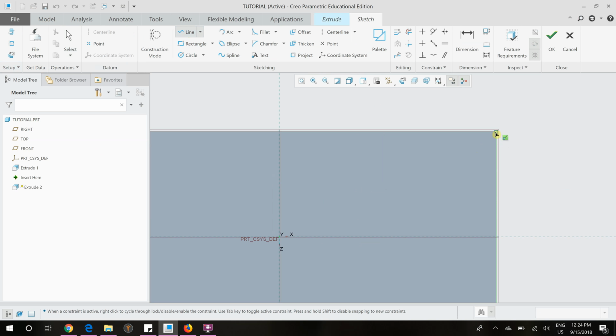So say we want it to be centered, let's say an inch from each edge. So we're going to measure down to the center of the hole. And now we can draw our circle. Let's say we want our screw holes to be 1/4 of an inch in diameter. So we're going to type that in.